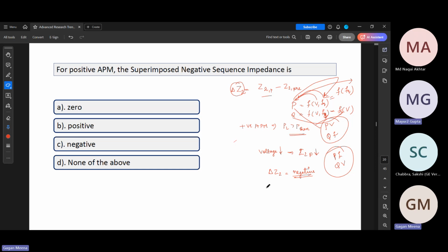If you go to the power system analysis books, and when you write P in terms of voltage and frequency, when we say this decoupling, we make that decoupling based upon certain assumptions, and those assumptions do not hold true for a distribution system. That is why we say that these two are not directly related.